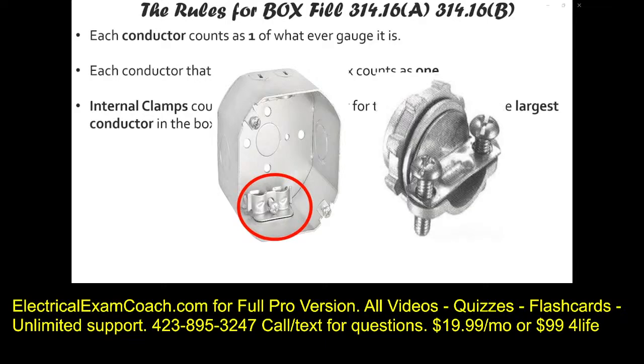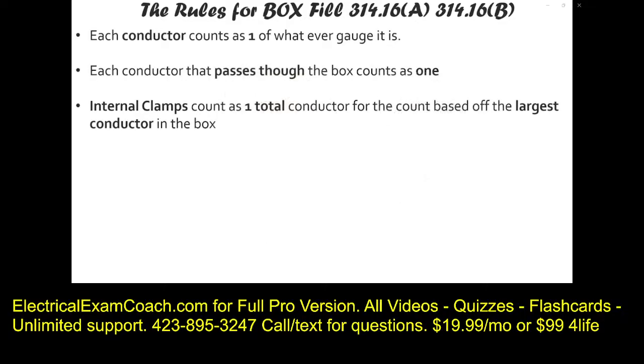This is an external clamp because the clamping mechanism is on the outside of the box, and we don't have to count those at all for box fill purposes.